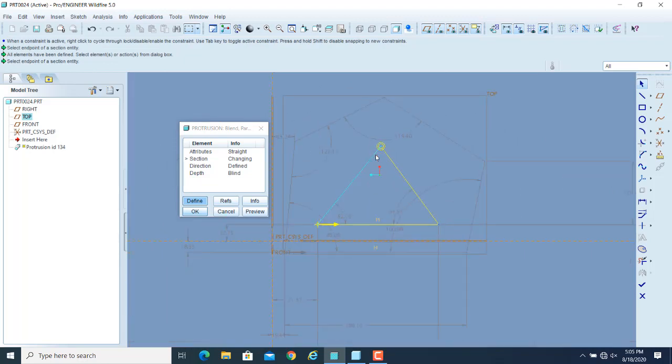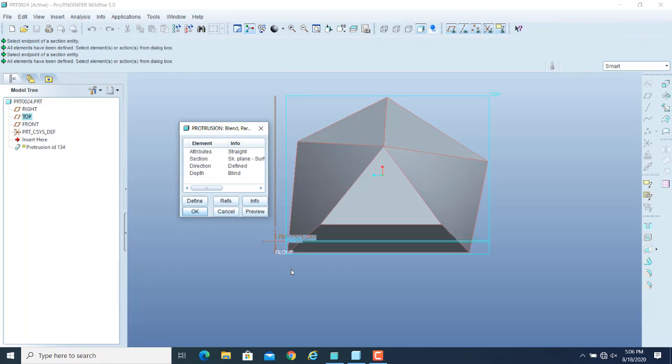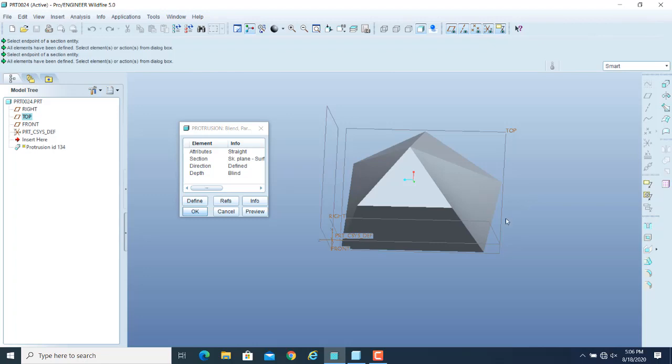This means that you can now join 3 other points to this one. So if I click on the check mark button and check the preview, you can see that the first point is connected to the first, second to the second, third, fourth and fifth to this one. So this is how you can use the blend option.